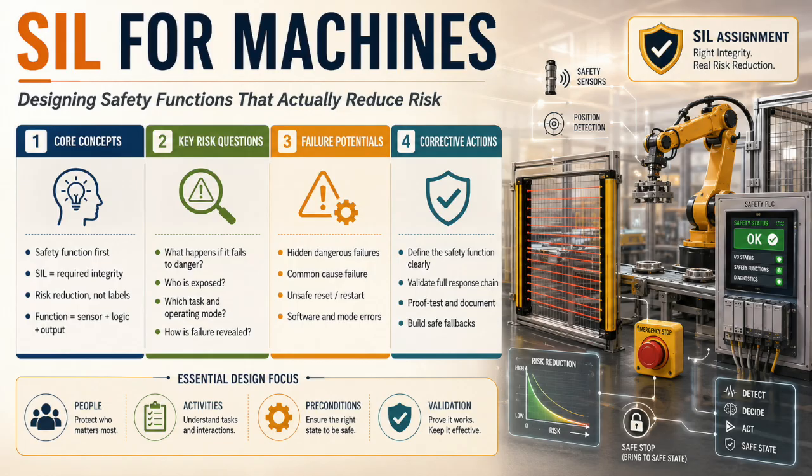And that complete function includes the sensor, logic solver, final element, wiring, diagnostics, software, reset philosophy, stopping time, human interaction, validation, proof testing, maintenance, and lifecycle control. So when someone says this device is SIL 2, your next question should be, but what is the safety function?